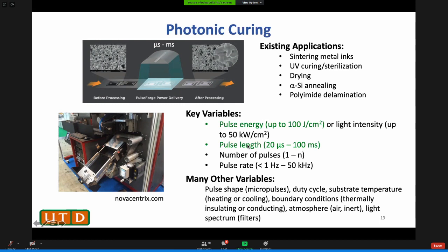And I'm plotting the substrate temperature at the bottom here. So all the heat, other than what is radiated out to the environment, is going to transfer to the substrate. The half-millisecond pulse is right here. But you can see that after that pulse ends, the film starts cooling down, losing energy to the air and transferring to the substrate. The substrate starts heating up.